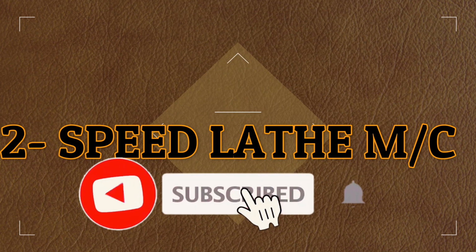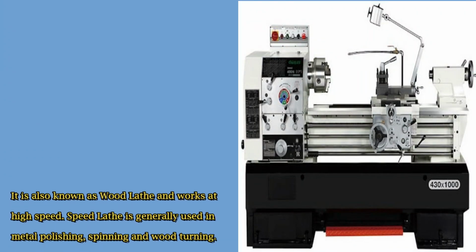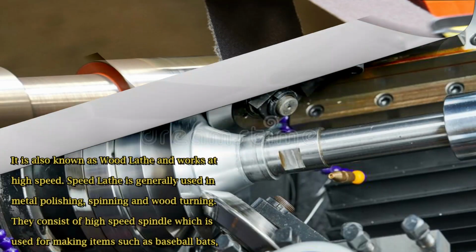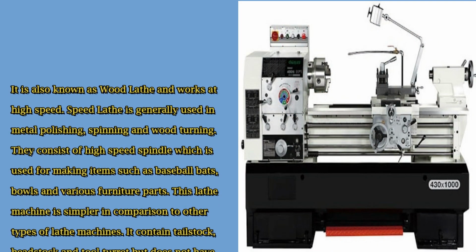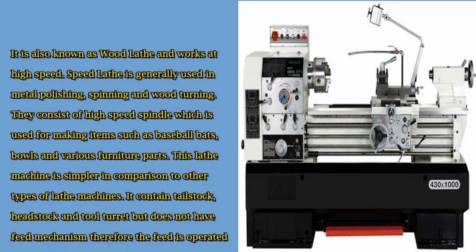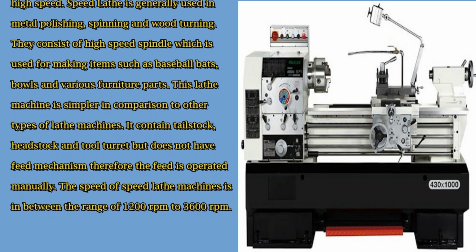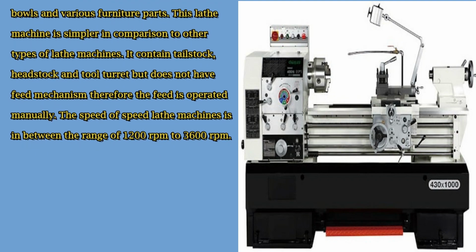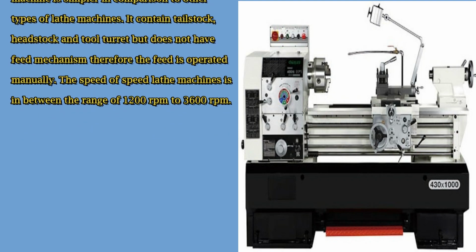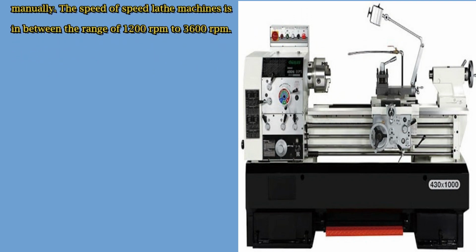2. Speed lathe machine. It is also known as wood lathe and works at high speed. Speed lathe is generally used in metal polishing, spinning and wood turning. They consist of a high-speed spindle which is used for making items such as baseball bats, bowls and various furniture parts. This lathe machine is simpler in comparison to other types of lathe machines. It contains tailstock, headstock and tool turret but does not have a feed mechanism, therefore the feed is operated manually. The speed of speed lathe machines is in the range of 1200 rpm to 3600 rpm.